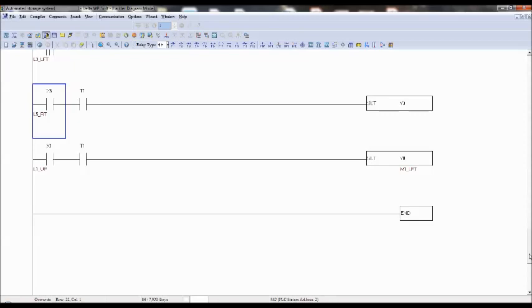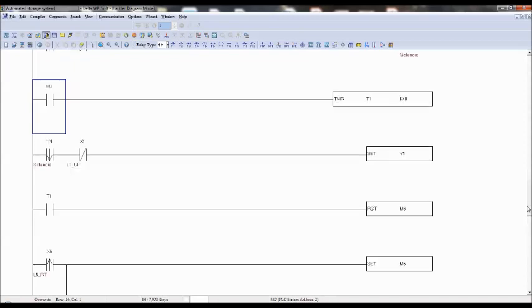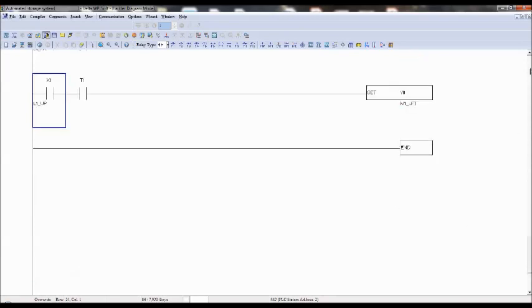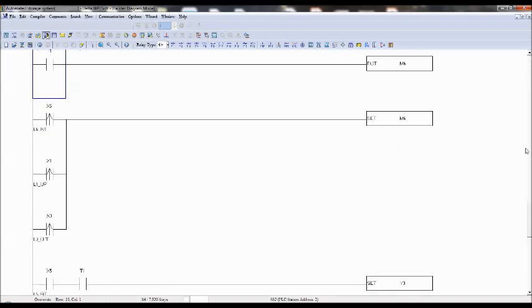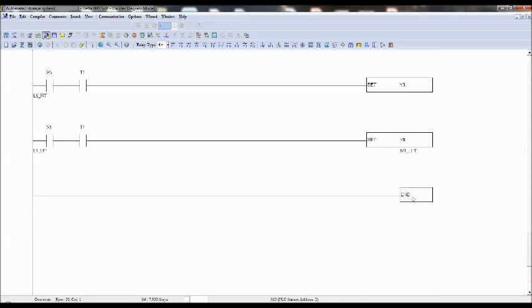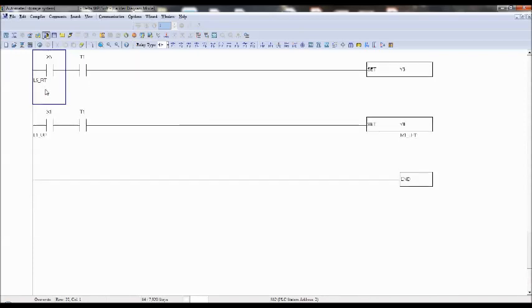Look at here. See, solenoid will take 4 seconds of time, T1. See here, whenever it has reached the right position, see this is the command. Whenever it reaches the x-axis rightmost position plus timer is on, that means solenoid has completed extending and retracting, and then it gives a command for y3, which is nothing but upward direction.